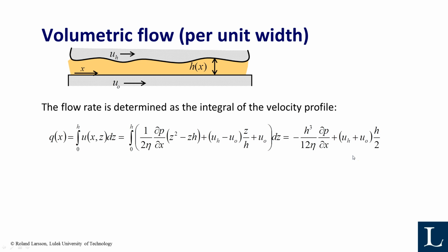So if you assume now that this is a damper chamber, you have the P out pressure out here, and you have some outlet pressure here, which can be assumed to be 0. And in our case, this film is constant, so it's a constant film all the way here.